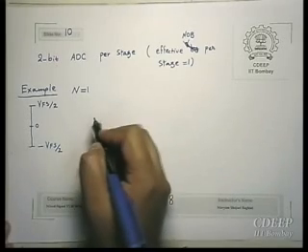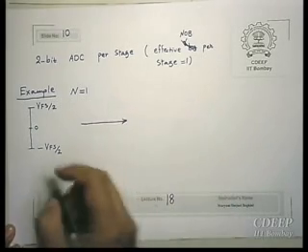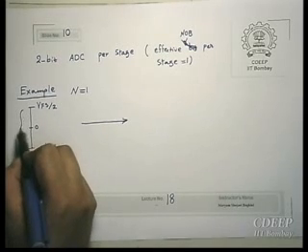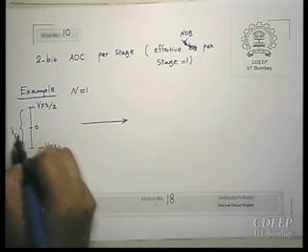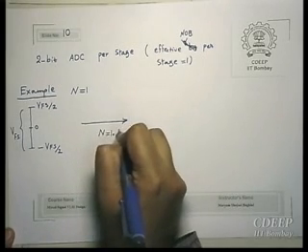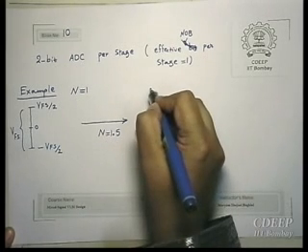So we make it, how many reference levels do we have? Actually it is 2, right? 0 and minus V full scale by 2. Or if we use positive values, it will be 0 and plus V full scale by 2. Total range still is V full scale. Okay. Now let us make n 1.5. So what does it mean, 1.5? Eventually, it is just a concept.